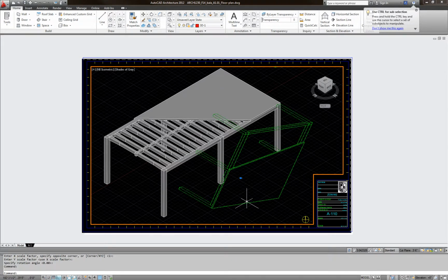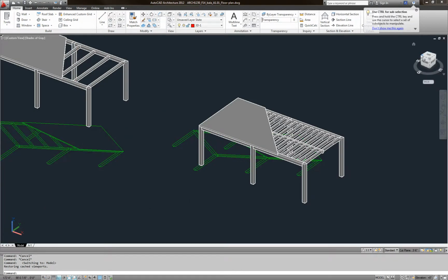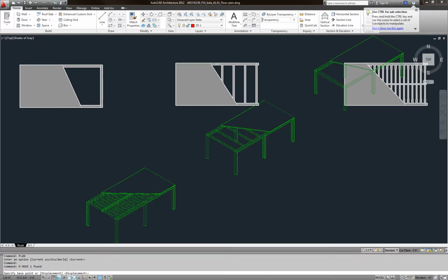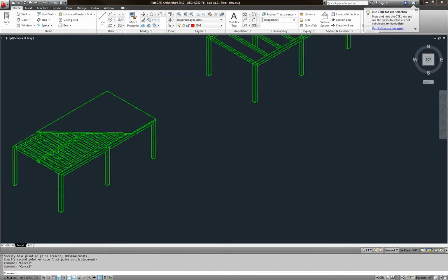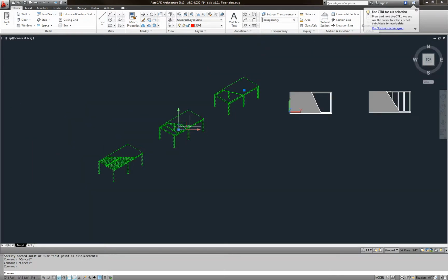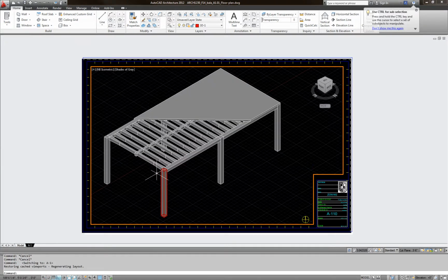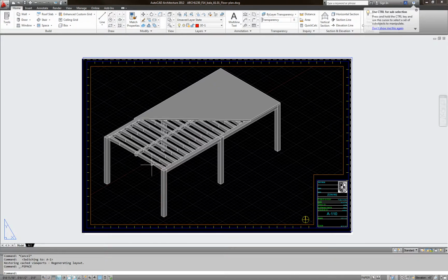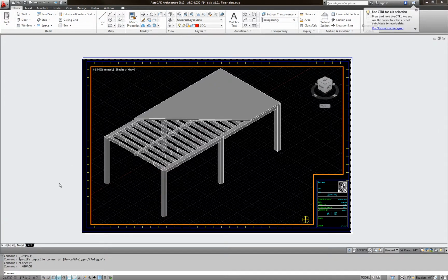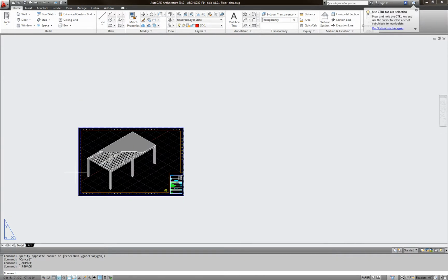Okay, so now since it's locked in spot, you could go to the top view, or you could type in plan, PLAN. So now you have these 3D objects in 2D drawings, whatever we did. At the same time, if I explode this, it's a block, I can copy this, Control C. Then I will go to my paper space here. I'm going to come out of this. See, I'm not inside the viewport now, I'm outside the viewport. And this time I'm going to paste by Shift Control V, which will give you a quick block for you.